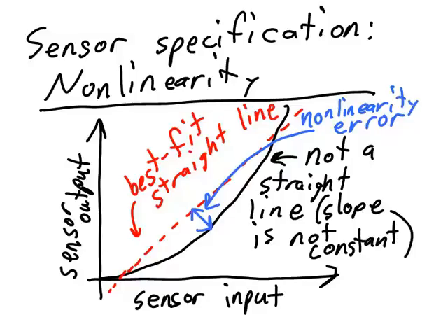But if we are going to use that photocell to measure distance, we might want to know the amount of nonlinearity error when the sensor is measuring meters of distance versus voltage, the thing that we will measure. In that case, we would need to find the sensor response curve ourselves by testing the sensor, and then use our own plot to best fit a straight line and calculate the nonlinearity error.